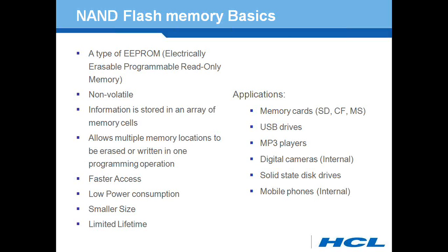Compared to MLC, SLC has high data reliability, which requires very little error correction coding and wear leveling algorithm compared to an MLC flash. And flash, as we mentioned in the introduction, is small in size and its power consumption is also very low compared to other storage devices. The main property is that it is non-volatile, which doesn't require power to hold the contents of what was stored inside the physical memory.